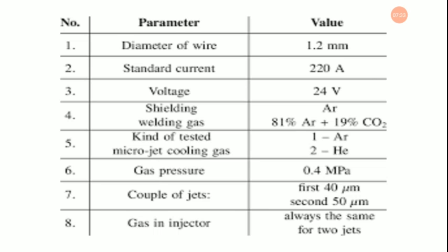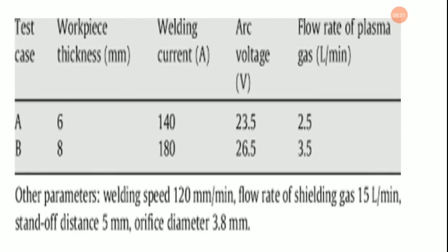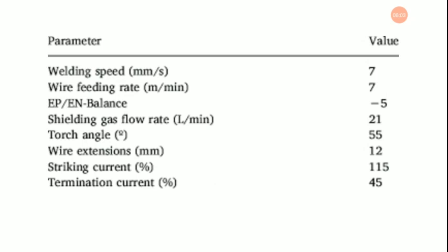The chemical composition of both base metal and filler were measured by the method of spectrospark emission using a spark analyzer, and the working range of peak current IP, base current IB, welding speed S, frequency F, pulse on time PON, and gas flow rate GF has been explored by inspecting bead appearance, bead contour, and for any visual defects.